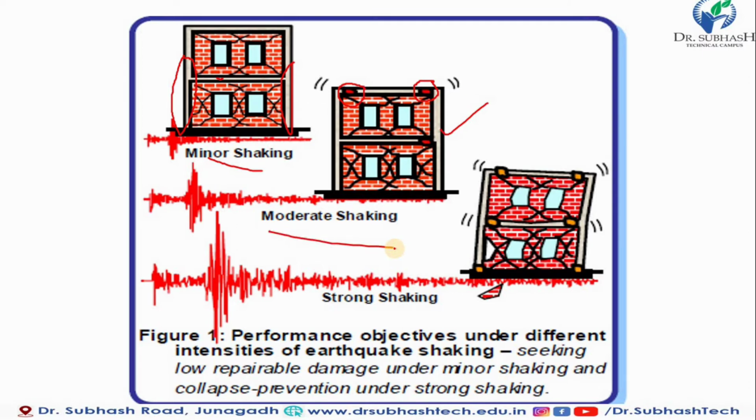Now strong shaking and the rare earthquake. Our horizontal member is also collapsed. Our masonry is also damaged, and we have to replace it, but still our building has not collapsed. So this shows the importance of the vertical member and the joint between horizontal and vertical members. How should we create such a joint? Under strong shaking, our building should not collapse.